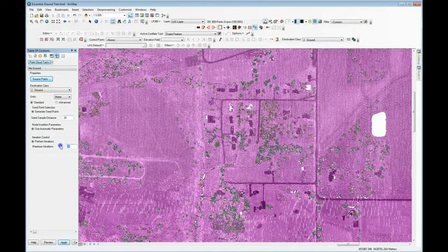Now I always like to start this out fairly small, let's say 4, so that I can get an idea of what my settings are going to do without having to spend a long time waiting on the algorithm to complete. After you've set all of the parameters, make sure that you press apply. This is one of the biggest mistakes in point cloud tasks, and it is telling me that I probably ought to have our developers change this interface. If you do not press apply, you'll be using whatever the prior parameters were before you changed filter settings.